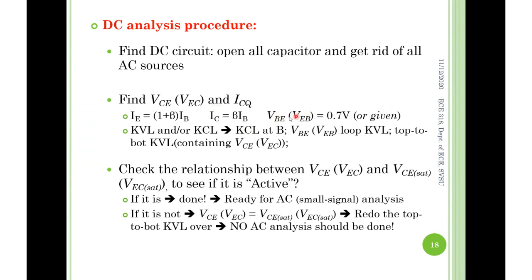Now look at this equation. What do you find? For a fixed material, the VBE is a constant value, and will be given. Remember in the lab today, for a silicon material, VBE equals 0.7. For germanium, what's the VBE value? Anyone still remember? Today's lab. Was it 0.3? Good, very good. Anyways, it's lower. It's a different material. You fix the material, then VBE is fixed. Of course, it might be VEB, depending on NPN or PNP, right?